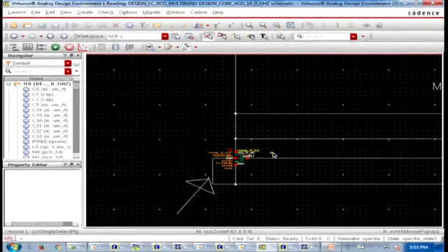You have to reduce the inductance value. There is no other choice. So the TSMC process actually gives a very nice script, which will show you it is theoretically possible, but practically it is really impossible to find a proper inductance value for your frequency of operation.